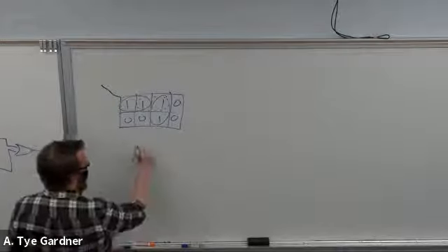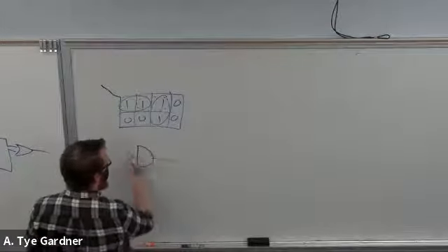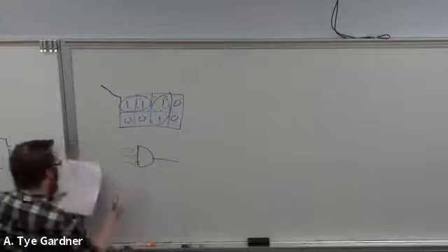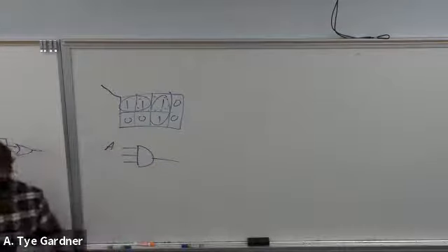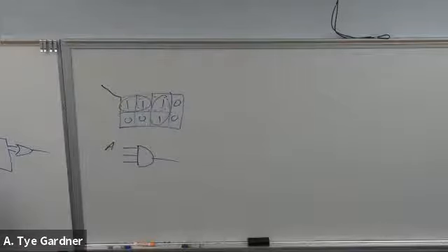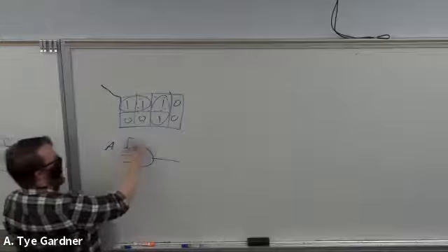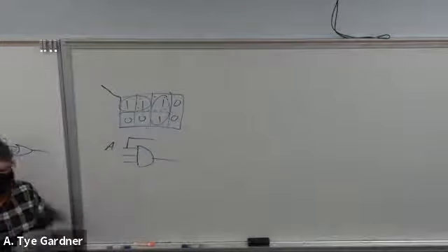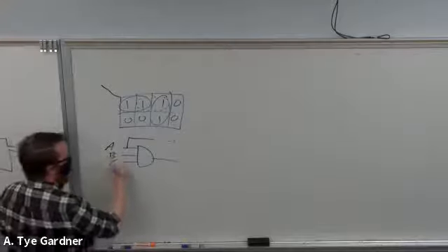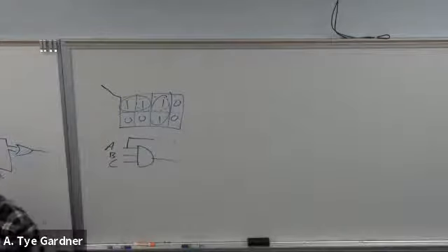Right, so I have an AND gate, and I have a signal A. Let's say that A is my signal that I'm worried about having a hazard on. There's some other circuit that A is connected to, but let's just worry about this AND gate. What do I do with signals B and C to prime the circuit?